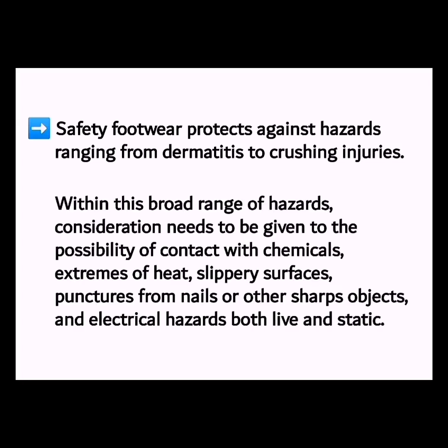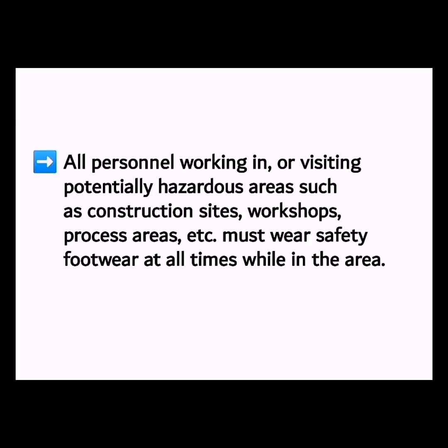Foot protection. Safety footwear protects against hazards ranging from dermatitis to crushing injuries. Within this broad range of hazards, consideration needs to be given to the possibility of contact with chemicals, extremes of heat, slippery surfaces, punctures from nails or other sharp objects, and electrical hazards, both live and static. All personnel working in or visiting potentially hazardous areas such as construction sites, workshops, process areas, etc., must wear safety footwear at all times while in the area.